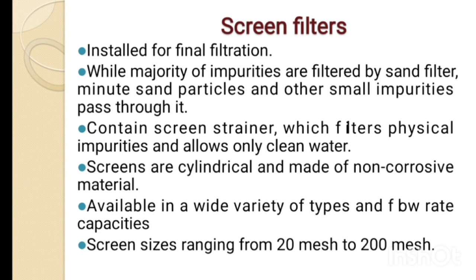Then screen filters. It is installed for final filtration, while a majority of the impurities are filtered by sand filters. So only the minute sand particles and other small impurities are filtered by these screen filters. These filters contain screens of cylindrical and non-corrosive material. It is available in wide varieties and types, and its screen sizes range from 20 to 200 mesh.